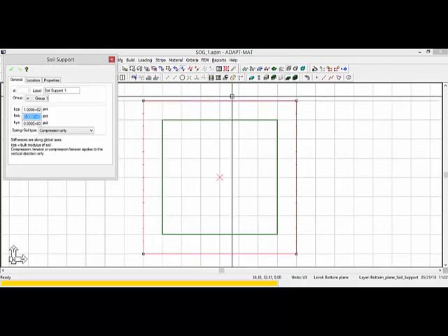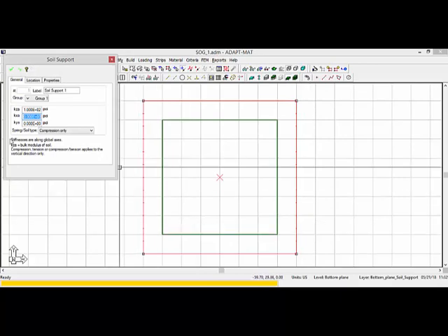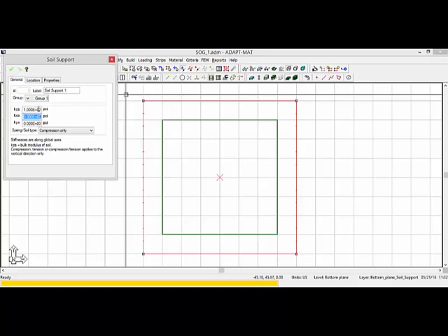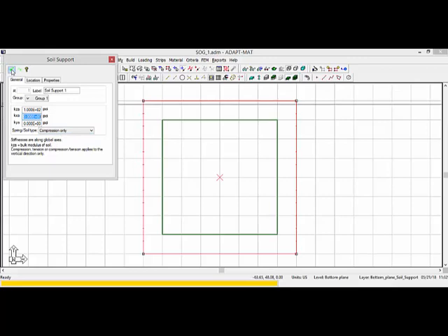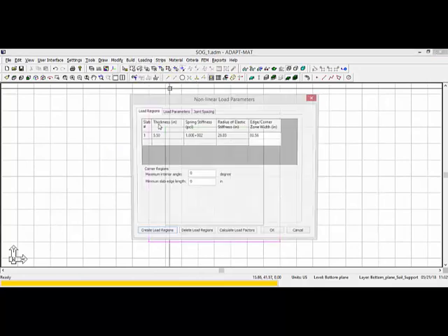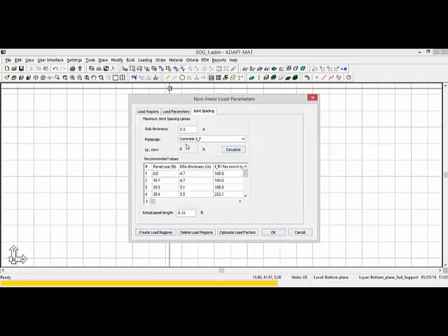So we'll double click on the soil spring. This is an area spring where we can enter the subgrade moduli for the soil, and we're going to leave this as is, at 100 pounds per cubic inch. Notice this is a compression only spring, and I'll select the green checkbox to close that. I'm now going to go back to loading, Still FRC. Under joint spacing, you can see based on the input that we've made, this chart below is really just a recommended value. So now we're going to actually calculate the maximum joint spacing for this slab thickness and this concrete type, and we'll select calculate.